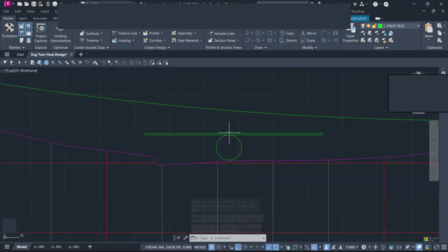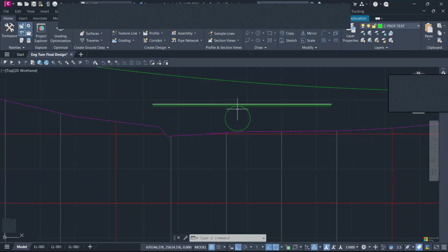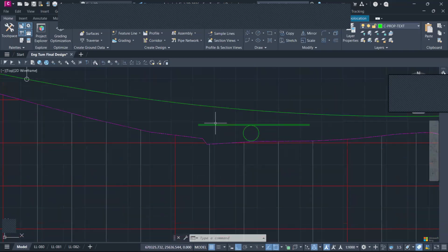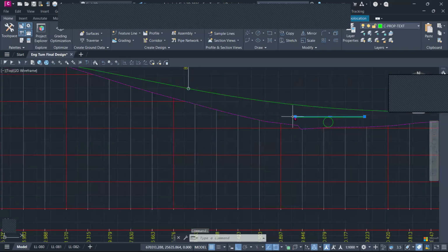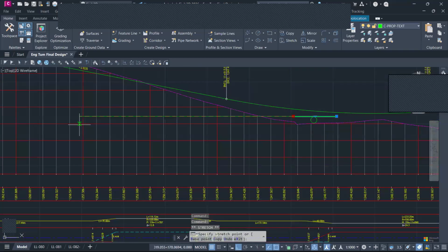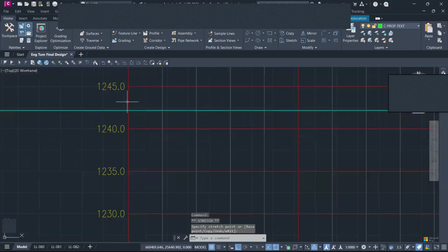So you make sure you account for it, so that as you position your culvert, you will have derived the invert levels from your profile. For example, we derive this point, you go straight all the way to this other point on the profile, and you can see the elevation for your culvert is at this specific point.